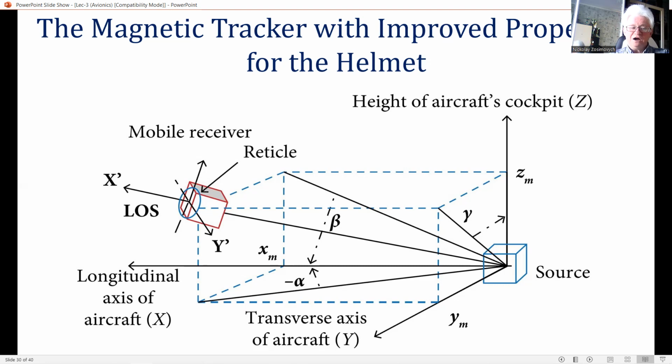This is because the pilot's direction of gaze is inferred from the helmet attitude measurement. The pilot can, in fact, experience great difficulty in keeping the helmet sight on the target when subjected to severe low-frequency vibration. This can result from the buffeting, which can be encountered at high subsonic speeds in turbulent air conditions at low altitude. The power spectrum of these buffeting vibrations can include significant levels in the 1 to 10 Hz frequency range, which the pilot is unable to follow and keep the aiming cross on the target.